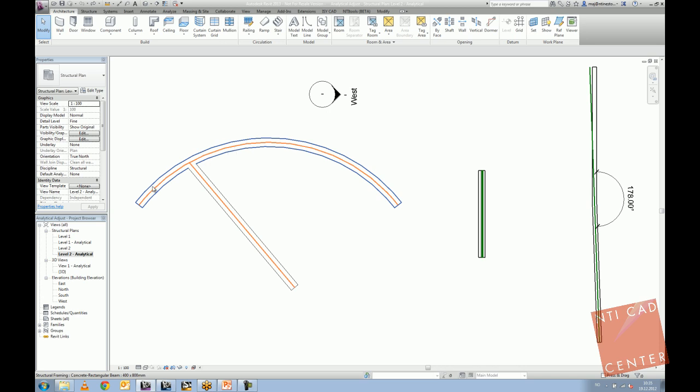If you have a curved element which is breaking down into thousands of small elements, and then you have a slab on top, the slab finite element mesh size will be really dense in this combination because it will try to snap to every node. That's something you really want to avoid. And you have possibilities to avoid it in Revit.